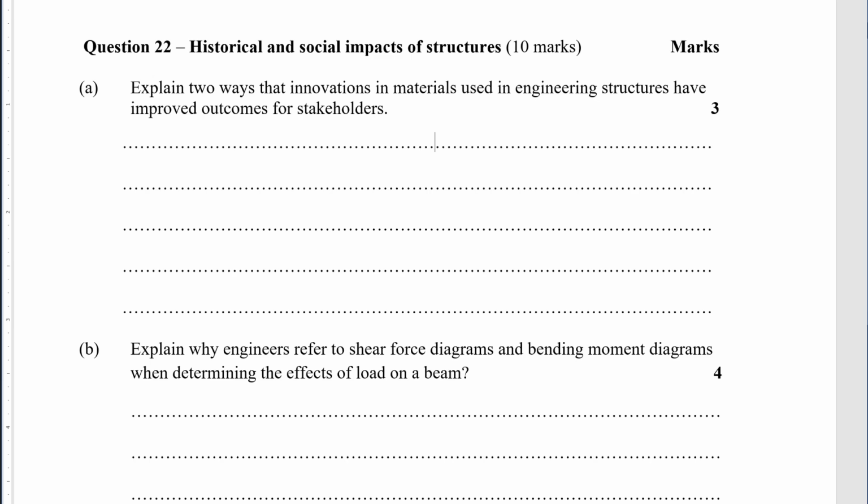There's a whole lot of other answers we could say. We could talk about the aesthetics. A lot of the time when people use these engineered timbers, they're doing it because they think it looks good. It's often used in showcase buildings, like universities or Parliament houses. It's also free of defects. What I'm trying to focus on is the fact that these days we can't really use large span timber without it being engineered timber. So that's an innovation that we required.